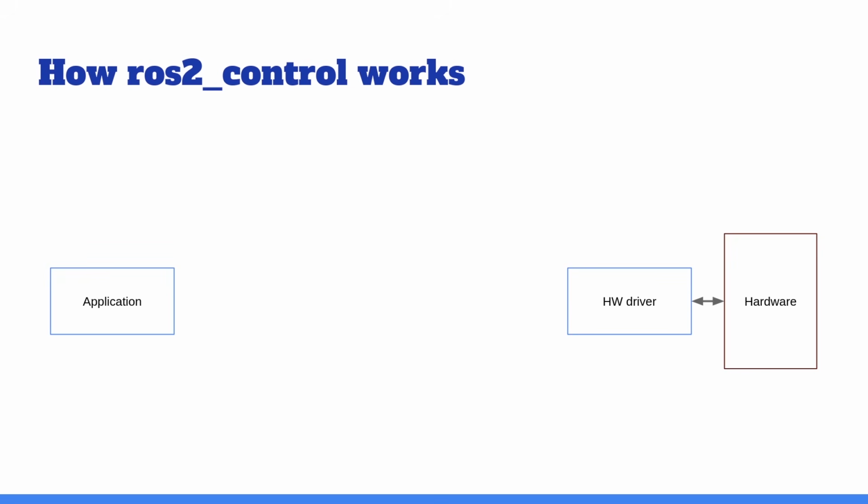First, we will need to add a hardware driver. This has nothing to do with ROS really, it's just a piece of code, like Python or C++ code, that's going to allow your computer to talk to the hardware. For example, you need to start communication with the hardware using a certain protocol like serial, I2C, CAN bus, etc. You're also going to have some functions so that you can correctly translate a command into something that the hardware can understand. Okay, so a hardware driver is not really specific to ROS, it's something you will do for any piece of hardware.